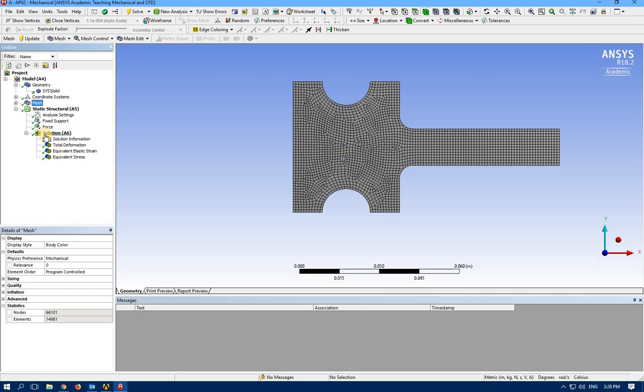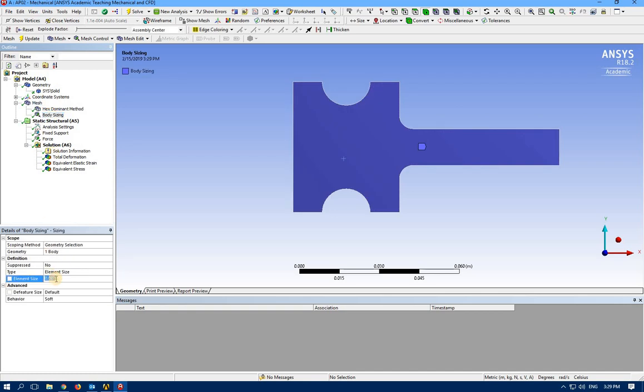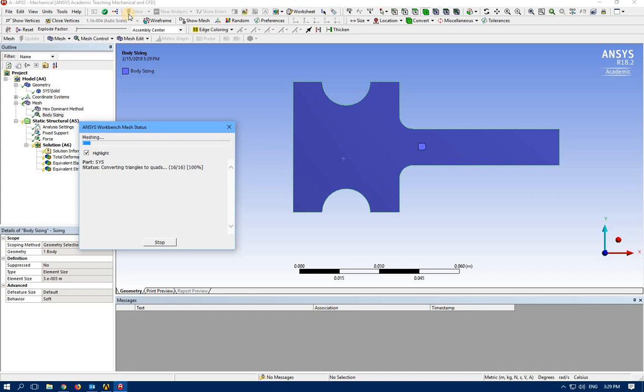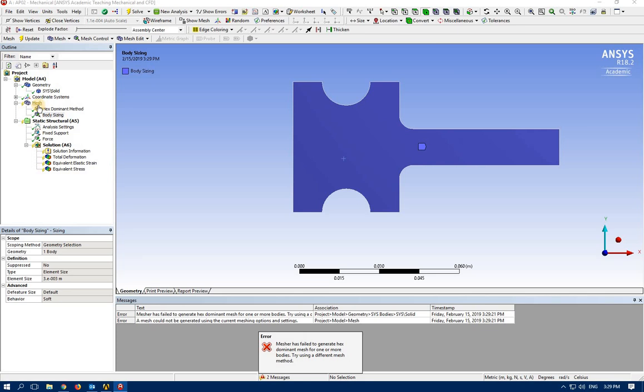So let's use sphere of influence. I'm going to increase a little bit the size of this to 3. So everything would be faster, and we don't need to wait long time for the results.